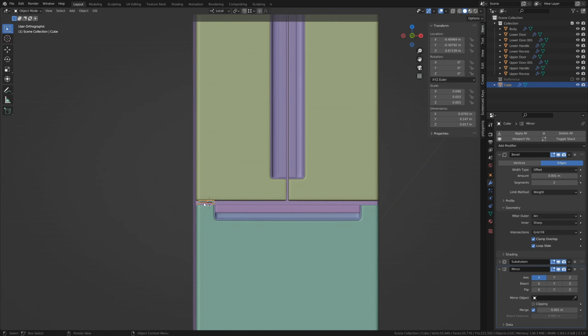So copy modifiers. And the mirror occurs on the origin point of the object. Another way to do this is to select the object, go over to the mirror modifier in the stack, and change the mirror object to something else that is centered. So let's take the eyedropper and select the body.